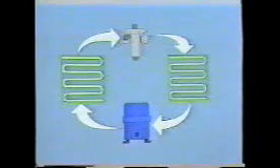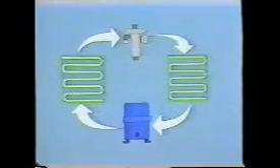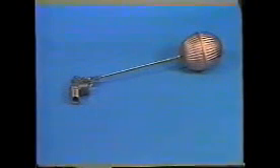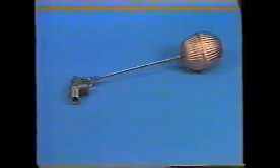Finally, we'll look at several different metering devices. These devices regulate the flow of refrigerant into the evaporator. We'll see one metering device that operates in response to temperature, and one that responds to pressure changes in the system. Another type of metering device physically restricts refrigerant flow. And still another type operates on the basis of refrigerant volume or level.